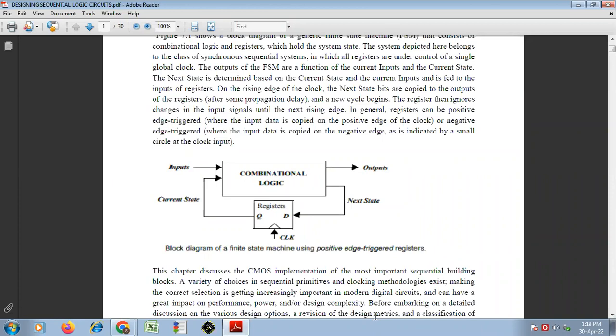So in most cases, it's a D flip-flop. It's a D flip-flop as a storing element, or you can say a register also, which can hold that data unless and until the next clock pulse triggers the flip-flop. Then it will pass whatever is stored to the output, and it will let in another input bit. So that's the general working of a D flip-flop. So a D flip-flop can act as a storing element or a register, you can say. Right. Now, this is the general definition and general idea of a sequential circuit.